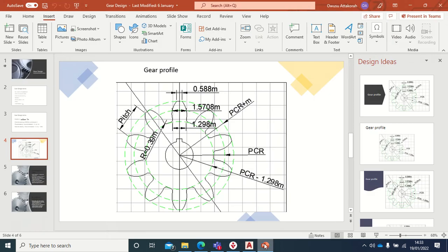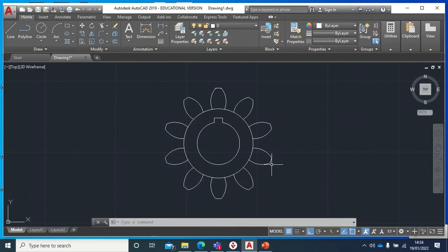Okay, cool. Let's come here. You see, there is an arc here. Where is that arc? Yes, there is this arc here. Can you see where my cursor is? Yeah. The arc is 0.39 times the module there. So please multiply 0.39 times the 6.5 and let's see what we get. Maybe 2.5 something. Yeah, times 6.5. Yeah, 2.535.